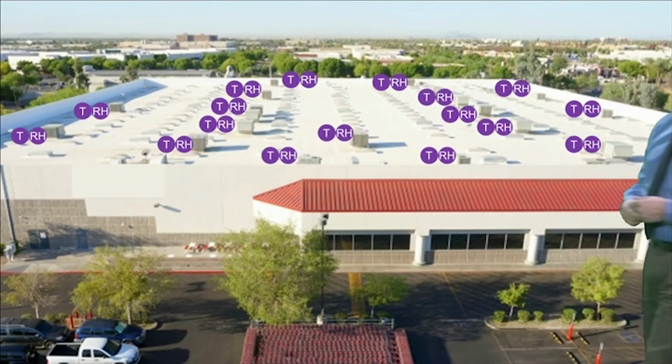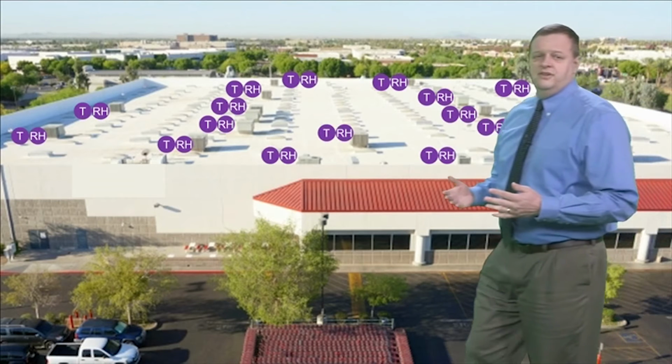As an example, consider a large retail store that's served by several package rooftop units, each equipped with an economizer. Now in a humid climate, an enthalpy-based high-limit shutoff strategy might provide the most energy savings. To implement this strategy, one approach might be to equip each unit with its own temperature and humidity sensors. But when you consider the added cost of the humidity sensors, the risk of inaccuracy, and the cost for periodic calibration, some clients might just elect to use simple fixed dry bulb control instead. But there are other options.